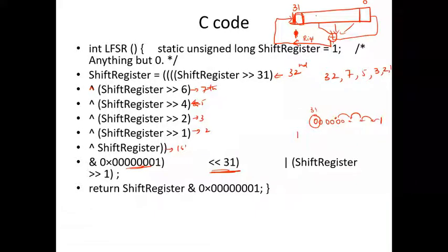After that, whatever was the previous content of the shift register, say something like 10, 10, 111, that content is added back. Once we do that, we do a right shift by 1 bit, taking the first bit outside. After every feedback which is generated, a right shift should happen.